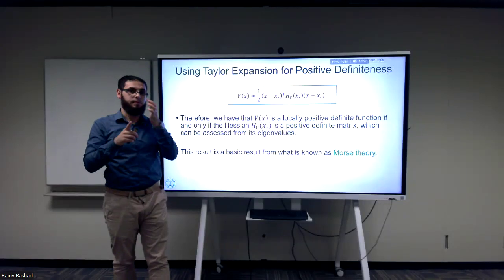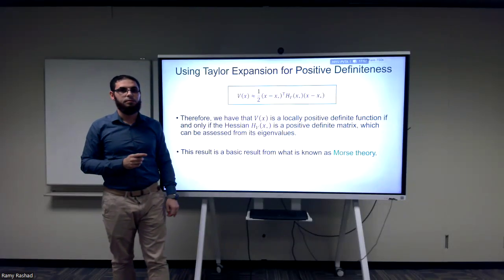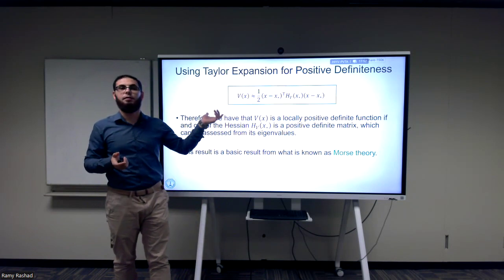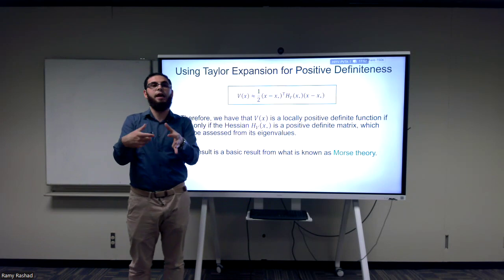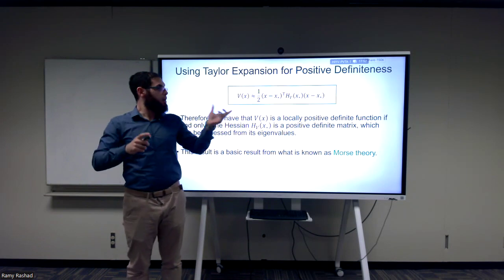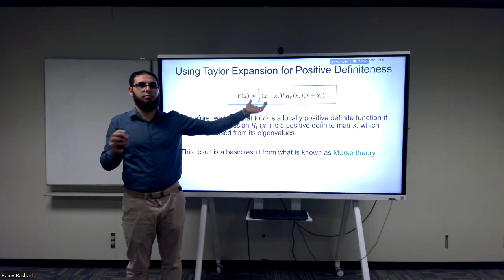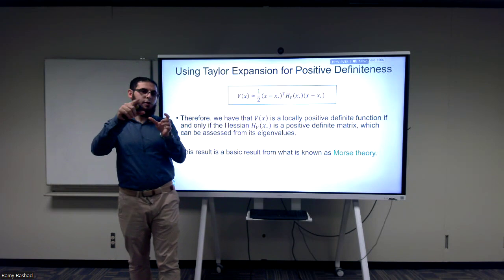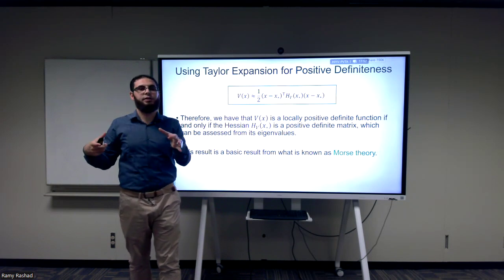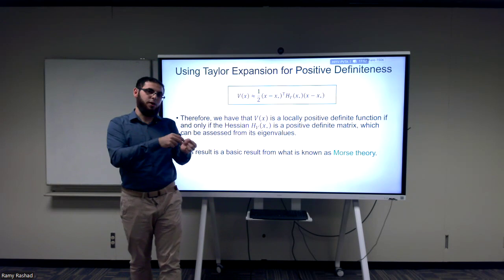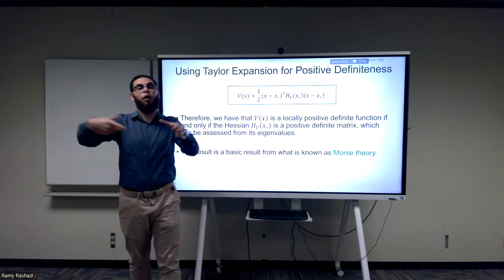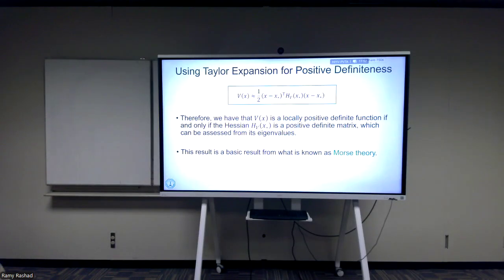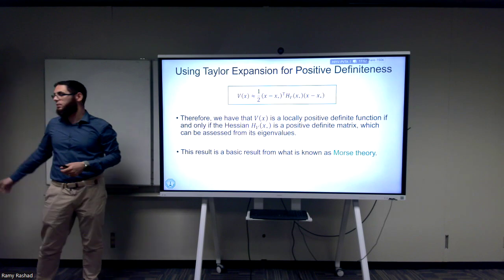But locally, how long is the range? Very good question. This doesn't say anything. Locally means you're in a small neighborhood. You don't have any way, by this equation, to quantify it. Now you're asking about this idea of domain of attraction. If I show that an equilibrium point is locally asymptotically stable, how big is this region where I can start near it and converge to it? You're going to talk about the domain of attraction.